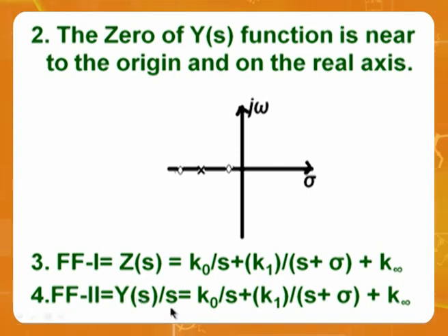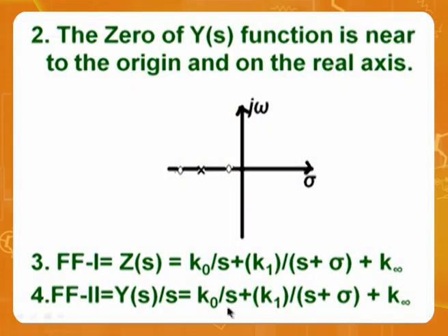You know why? If you take Y of s, you will get an inductance. If you take Y of s by s, you will get a resistor. So to avoid the inductor in RC synthesis, admittance should be divided by s. Are you able to understand?